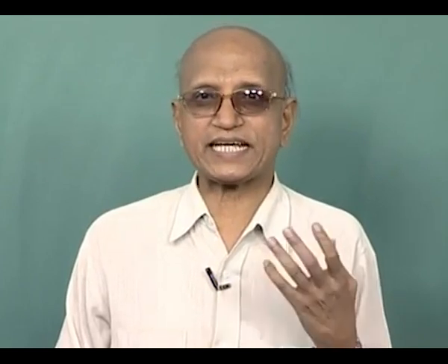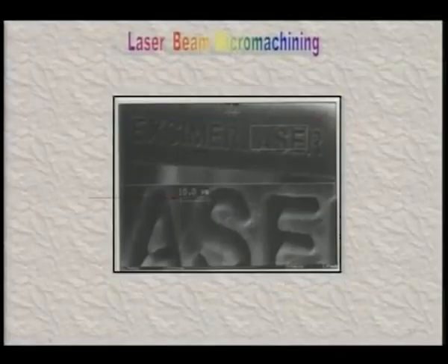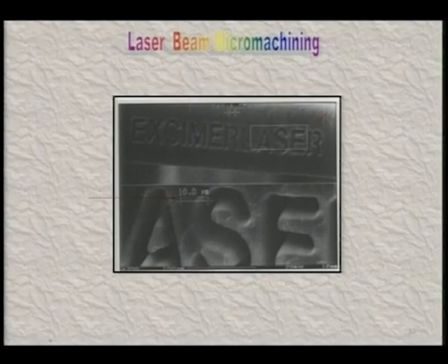So, now you can think of the capabilities of excimer laser in marking or cutting material like human hair also, and the bottom part clearly shows how accurately and nicely the letters have been written on the human hair. So, this indicates the capabilities of micro machining of the laser beam setup, and this is the excimer laser, which is a heatless process.